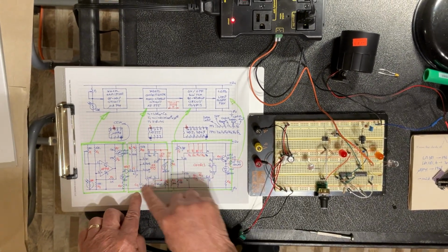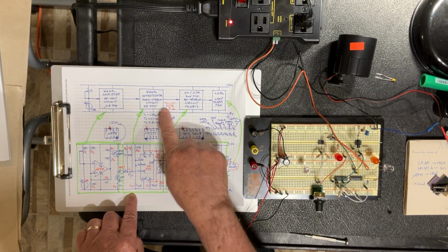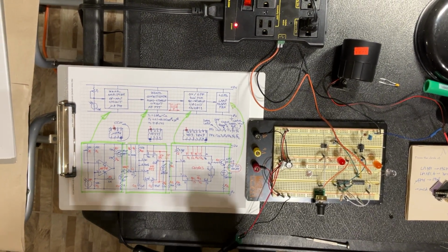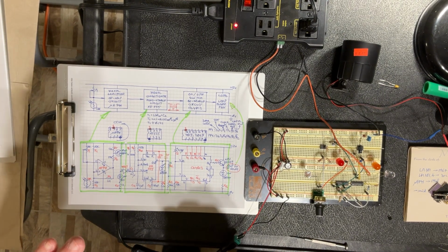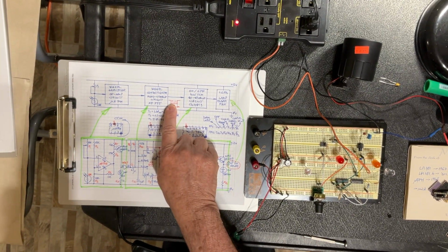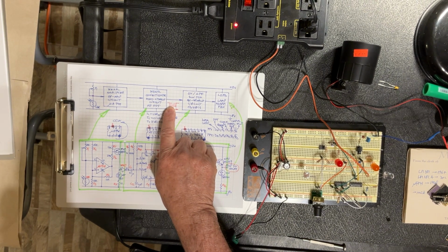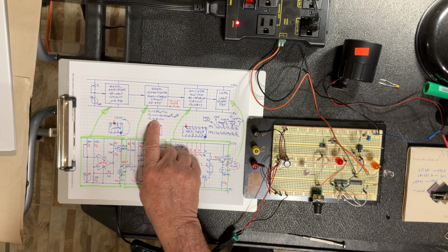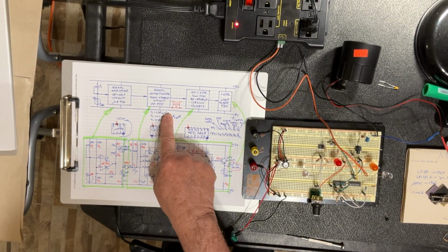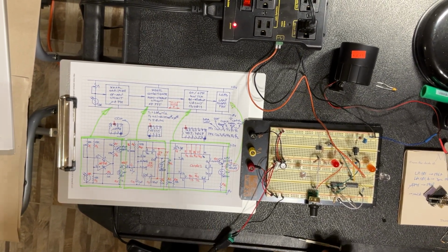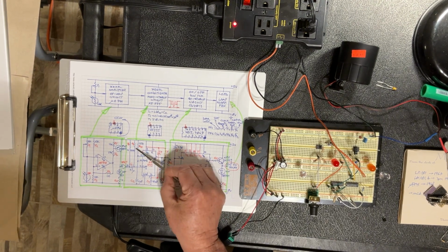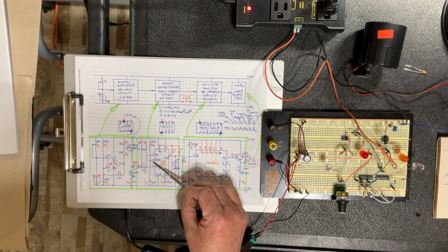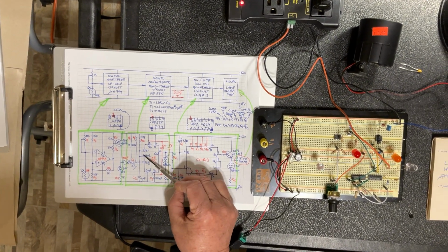This was the stage about the 555 used as a monostable circuit. This is the monostable, meaning it has a stable state, which is the on state, and you can get it off of that state for a limited time. What is the limited time? It's the duration we use the formula for, 1.1 times the resistor times the capacitor. Not any resistor or any capacitor, but only these ones here, the resistor 10 and the capacitor 2, the ones connected to pins 6 and 7.